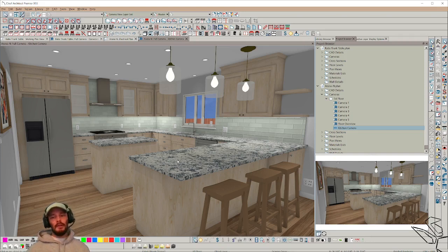I really encourage you guys to save a camera, do not move its position. If you want to move a camera, you should make a duplicate, because if you're doing a rendering and you need to go append some new information to that rendering, you want to have that same angle of camera. It's particularly useful if you decide after the fact that you want to go do a before after shot. And then you can Control Alt V, hold position your camera into your as built and get the same shot from your as built as from your really nice shiny rendering that you just produced.